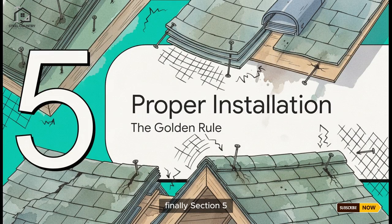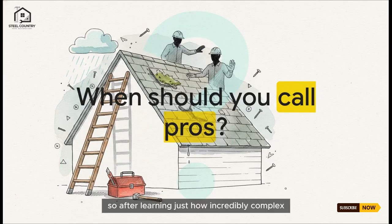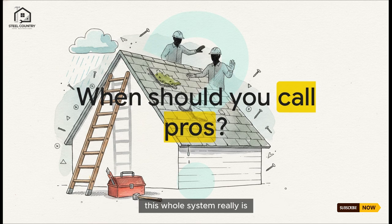Finally, Section 5, Proper installation and fastening. The golden rule of roofing installation ultimately comes down to the fastening. Nails must be driven perfectly straight and be absolutely flush with the shingle surface. It's that simple, but so often messed up. If a nail is overdriven, it cuts right into the shingle mat. If it's underdriven or crooked, it leaves the shingle totally vulnerable to catching the wind and tearing right off the deck.